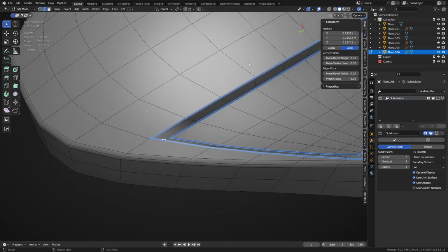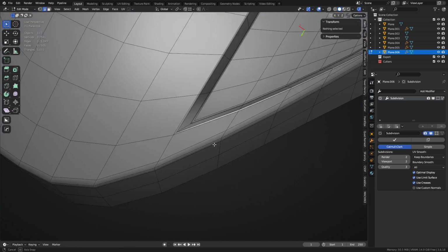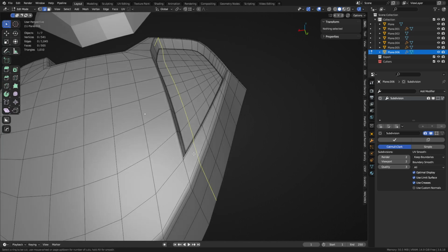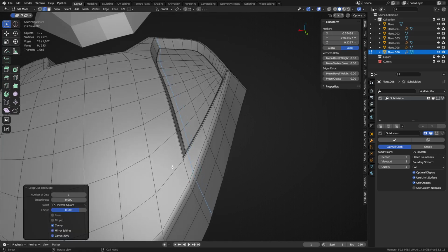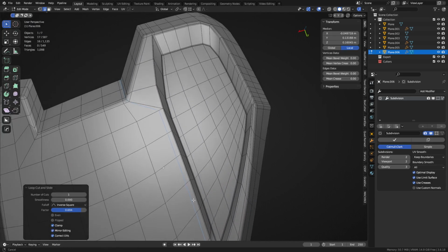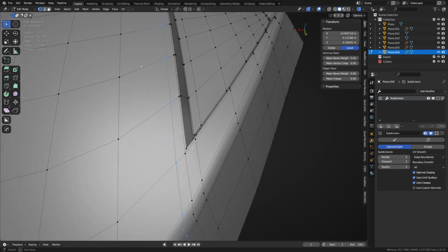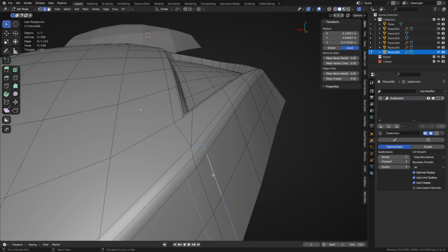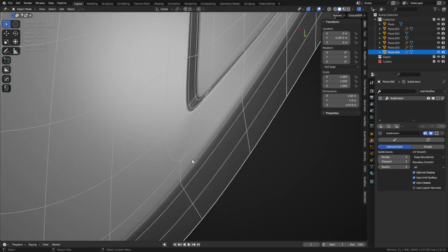Some of these corners may not be doing exactly what you want either. You want to sharpen them up perhaps. You're going to have to do loop cuts. Okay. And this is going to terrify some of you, but you loop cut. And for now, that should do okay. But right here, we can merge at center, dissolve these. Okay. You can do this number.